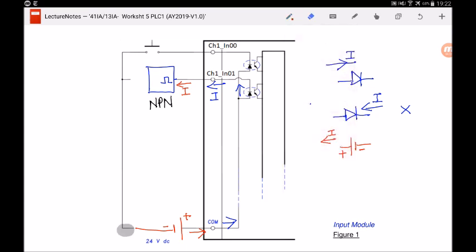As you can see over here, this path from the battery source is negative. So this entire path here is negative. So I will label here minus. Minus has to be connected to minus. So how about the plus? Well, I can just draw over here. And I can draw a dotted line or even a straight path to show that the positive of the sensor is going to be connected to the positive of the power supply.